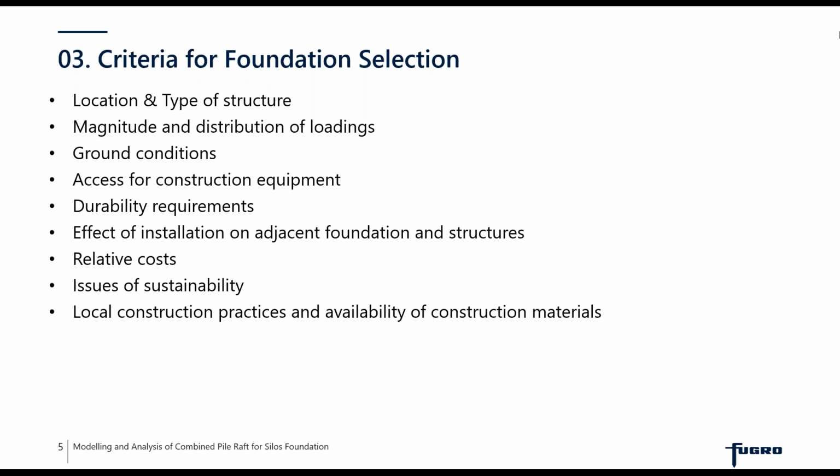But this is also governed by other criteria, for example, the access of the construction equipment, the durability and the sustainability issues, what is the effect of the installation of the foundation on the adjacent foundations and structures, the relative cost involved, and what are the local construction practices, and because of which what is the availability of the construction material at the site.